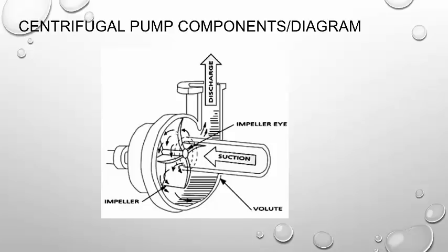So here we have a rotating center, and that happens to be your impeller, and specifically the eye of the impeller, and hopefully you can see that right here. The very center of that is the rotating center. That thing is moving. So you can imagine in your head water moving away from the rotating center. Now if I move that water away, ask yourself, what is going to happen?